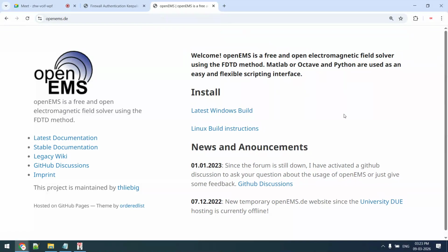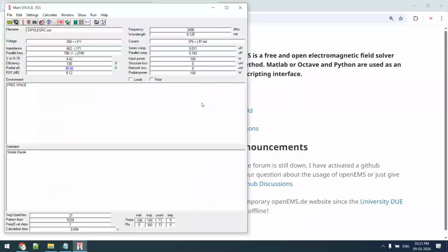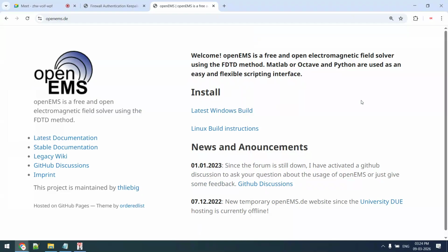So again, I'm repeating this part. In very simple language, if I want to create a wire-based antenna, for wire-based antenna, we work with NEC2, in very simple layman analogy. Whether it is whip antenna, dipole, wire antenna within sea, within ocean, wire antenna underwater, NEC2 is fine. But for microstrip patch antenna, in that case, Open EMS. Very simple.